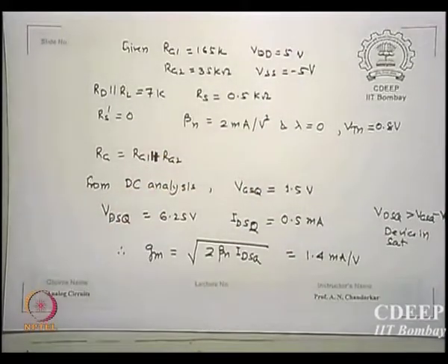Okay, in analog circuits, in my first slide I showed a dual rail supply. What does that mean? You may have a power supply at the top, the VDD side plus, and at the source side minus, but the actual voltage will be VDD minus VSS, and since VSS is minus, actually it sums. So if I want to use a 5 volt supply in total, what should VDD and VSS be if they are to be equal? 2.5 plus, minus 2.5 down.